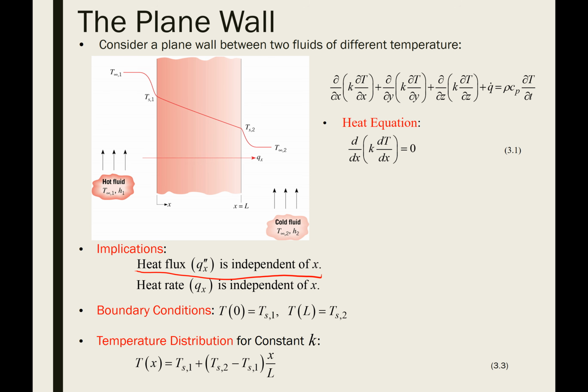So that gets more complicated than just applying the heat equation. If we wanted to quantify the amount of heat flowing all the way from here to all the way over here, first we're going to have to convect, then we'll have to conduct, and then we're going to have to convect again. So we need to factor all those different things happening into one single equation. Let's say we don't know the surface temperatures, we only know the air temperatures, then we'd have to consider all three of those modes.